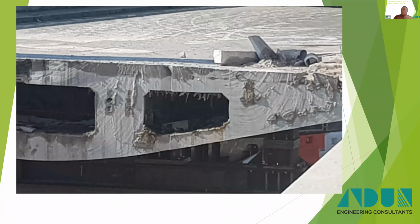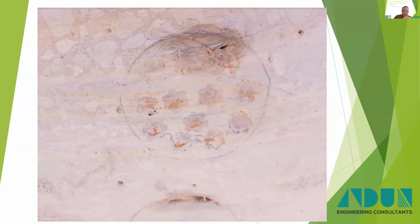It's just another close-up of one being cut through. And another one there. You can see that one's retracted slightly. Those ones haven't retracted at all, really. Whereas if they had been non-grouted, you can imagine that those tendons would have just disappeared into that void and you'd have lost any post-tension effect on that structure whatsoever. Though in this case, we'd analysed it and proved it would still work, but that's what would have happened.